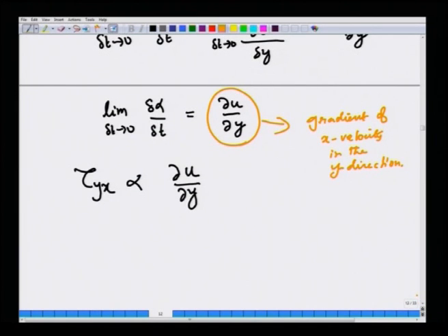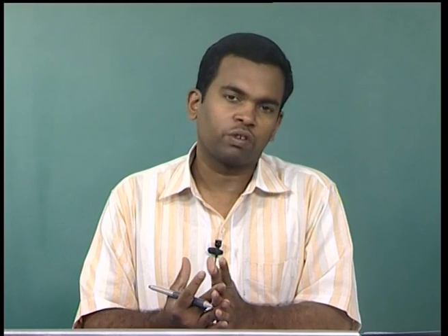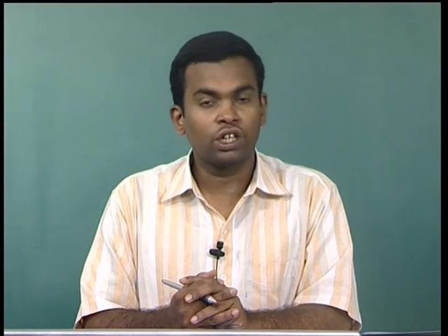So, in a fluid, in a liquid or a gas, the amount of stress that you exert will not be proportional to the deformation itself, it will be proportional to the rate at which you deform. In simple words, a fluid does not care how much you deform, rather it cares about how fast you deform, while a solid merely cares about how much you deform, because in an elastic solid, the stress is directly proportional to the strain, the amount of deformation, whereas in a fluid the stress is proportional to the rate at which you deform the fluid. So, if you deform the fluid quickly, the stresses generated will be more, while if you deform the fluid more slowly, the stresses generated will be less.